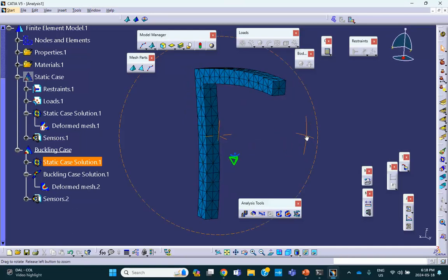It's the first buckling mode that you're interested in. Now notice that there's a lower buckling mode. In other words, if you had this fellow and you applied 26,000 on it, it will buckle, but out of plane. Just hypothetically, there may be constraints that prevent that buckling, then that's going to be safe, but then it buckles at 29,000 in plane.